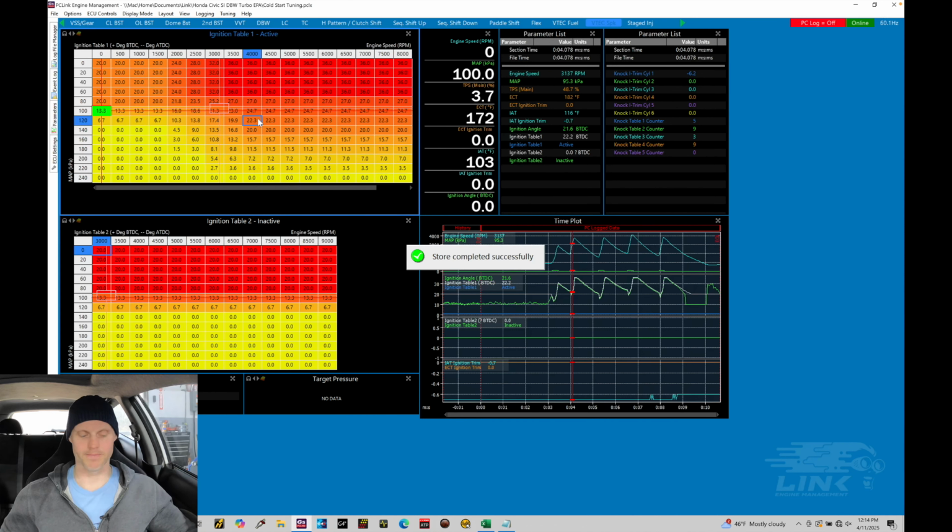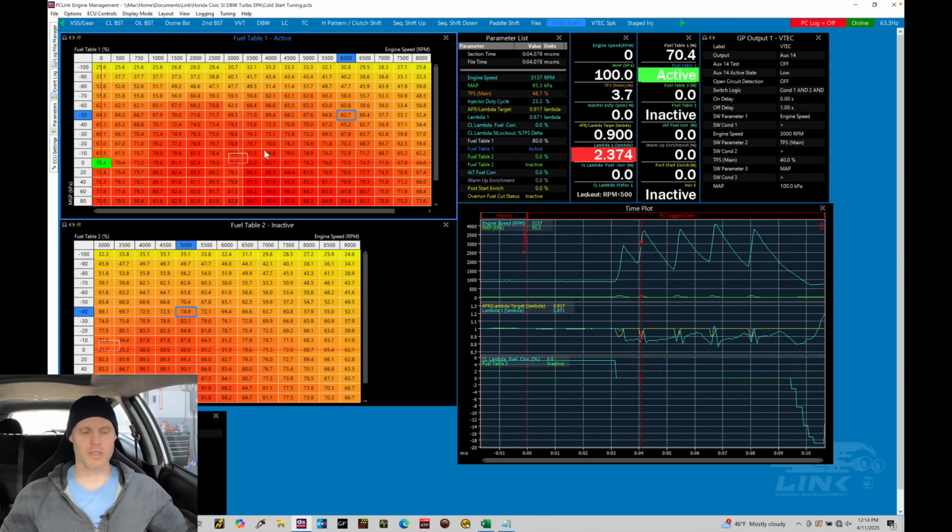So what we can do here is do two different things for moving forward for doing the calibrating and tuning in VTEC. One thing we can do here, let's go into the VE fuel. We've established in boost where we have our VE values. So these are the values that gave us the target lambda that we were asking for, about 0.82 to 0.78 lambda. So we can take these values and we can transpose them onto our VE table 2, or high cam. We can expect similar volumetric efficiency values on high cam.